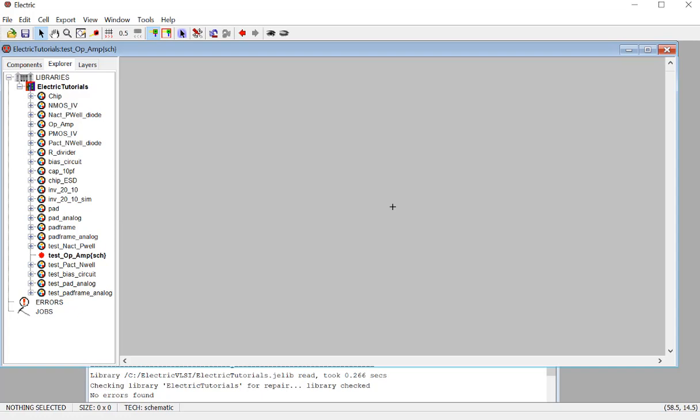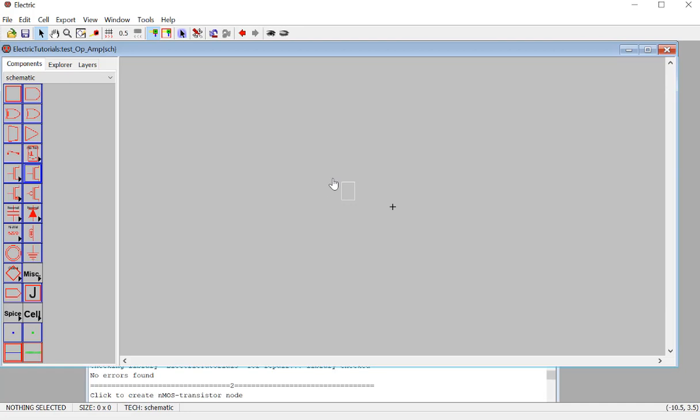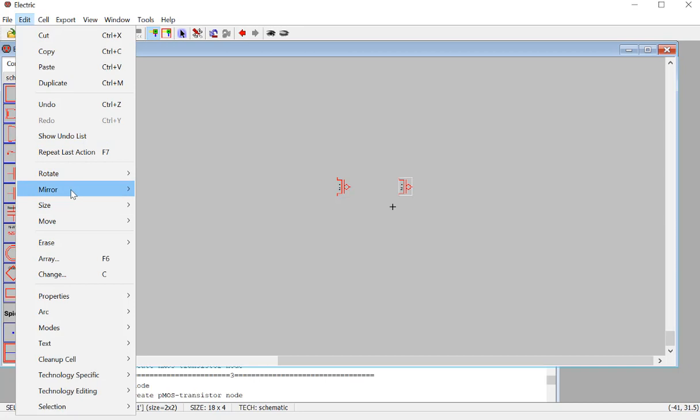So first of all, you need 22 by 2 PMOS on the top, and how many do you have? You have 2 of them, and then 10 by 2 NMOS transistors, and you have 6 of them. So let's find the first one, and we're going to rotate it like this. PMOS, right? Rotate it, and that's the first one, and we need the second one, and the second one needs to be mirrored.